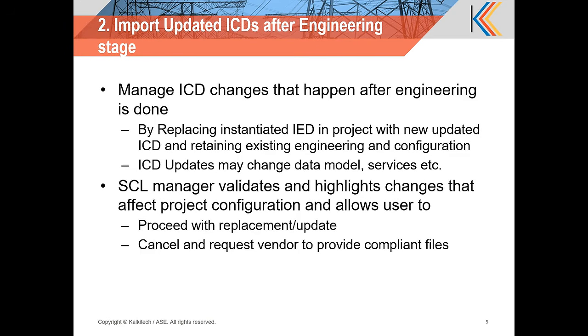The existing IEDs that are being used in the project have an updated ICD with some changes, maybe some changes in the data model, or maybe a firmware upgrade, or something has happened at the IED side. And there's a new ICD file. Now you don't want to restart from the beginning by importing, deleting the IED with all its engineering and restart from a fresh ICD. So here the use case is to replace an instantiated IED in a project with a new updated ICD without losing any of the existing engineering and the configuration.